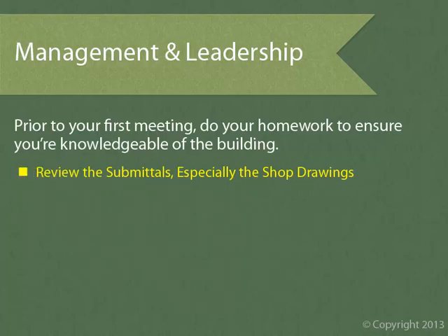First and foremost, review the submittals. Early in this course, I mentioned that the time to start your full-blown exterior skin coordination effort is when the submittals start coming in. Once you have the initial submittals from the major subs in hand, it's time to get rolling. But before gathering all the subs together, you must have reviewed and become familiar with their shop drawings, product data, etc. Now, you don't have to have all the answers yet, but you do at a bare minimum need to be familiar with their drawings and details. If you don't take the time for this review, you're going to look dumb in front of the subs at the first meeting, and your first impression is not going to be a good one. Like the old saying goes, you never get a second chance to make a first impression.